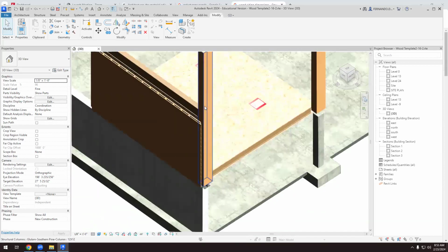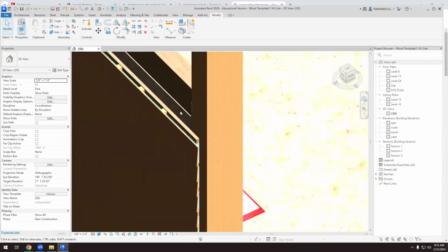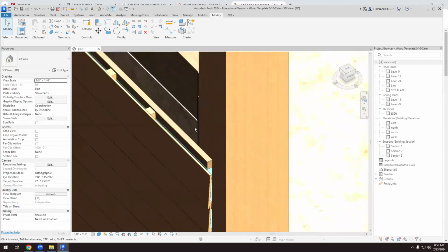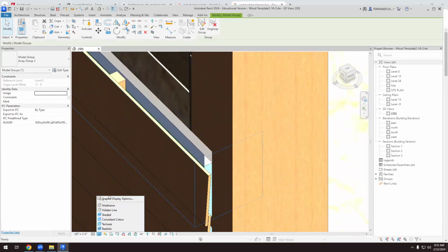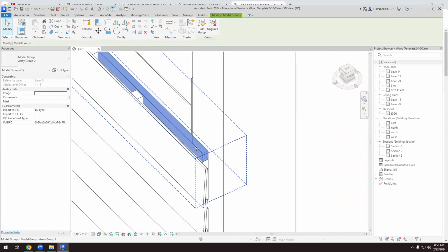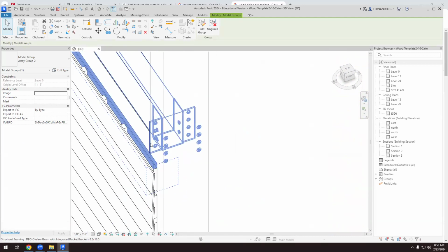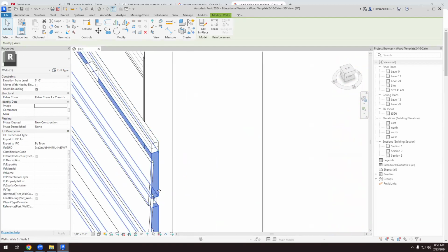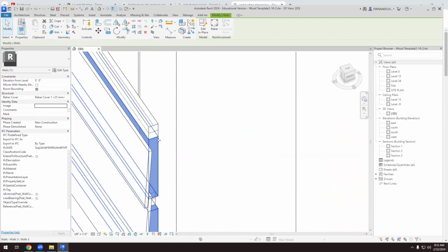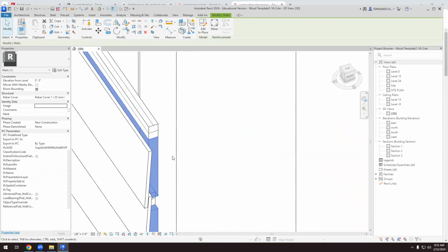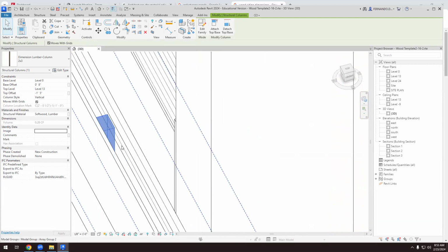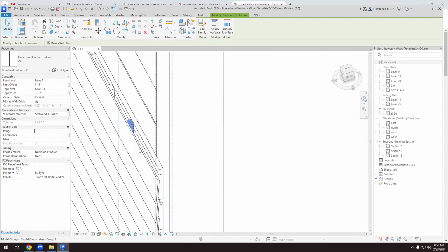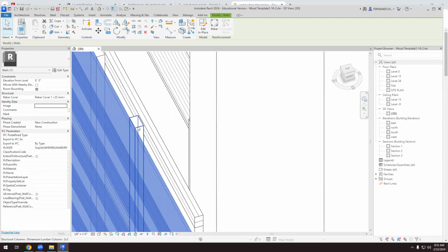Okay, so again, I'm repeating this. I have the board with the thermal insulation. Then I have these horizontal elements nailed to the structure. I have a thermal insulation, this rigid insulation between the horizontal elements. Then I have the vertical element nailed to the horizontal. There is an air gap here. And finally, I have the siding nailed to the vertical element.